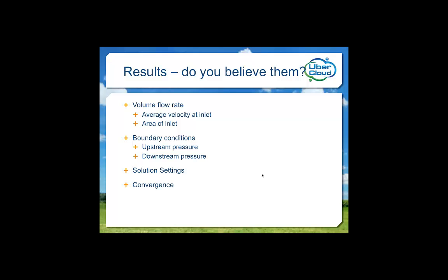I had seen that conversion is not a problem when the fluid remains a liquid, and all I needed was the program to return enough data to tell me when the fluid vaporizes, which happens as expected in choked flow. Still running simulations locally, I threw serious severe service conditions at the model and gave the results a hard look.